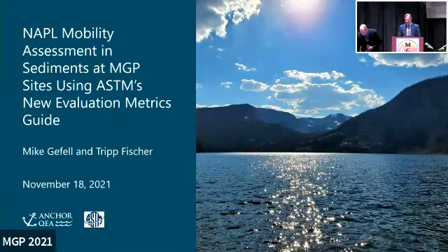Thanks, Tripp. And also thanks for leading our team so well, so skillfully, and for co-authoring this talk. So at many MGP sites, there are residuals of MGP operations that are present in sediment in the form of non-aqueous phase liquids. And so what I'm going to focus on is a new ASTM guide that presents specific processes, procedures, and methods to interpret the ability of the NAPL to actually move in the sediment.